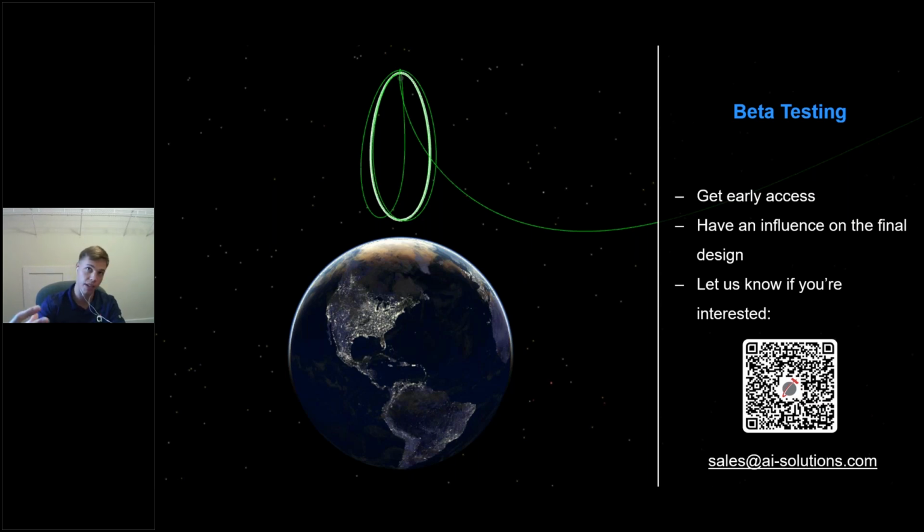At the end of that segment, place a constraint that says I want to be close to this asteroid or this planetary body to ensure we're doing a flyby. Take a second segment and just link it up to the back end of that first one. There's your flyby, and that's actually the method that was used to do the lunar flyby energy maximization example that was a few slides back.